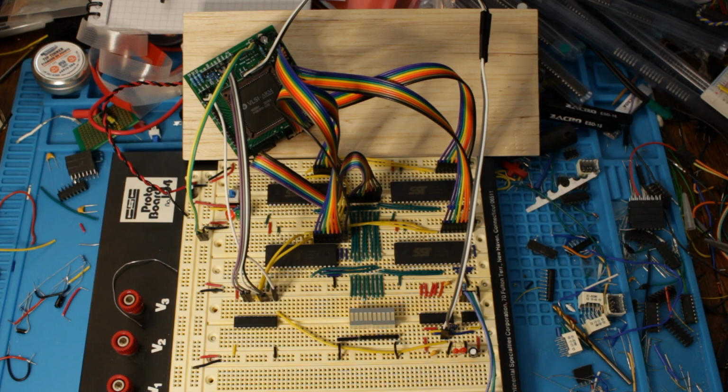And then the black, white, grey and purple are, I think, the byte versus word, read versus write, memory request and opcode signals. I've routed all of those through to the latch down here, even though we're not using the byte versus word or the opcode indicator.